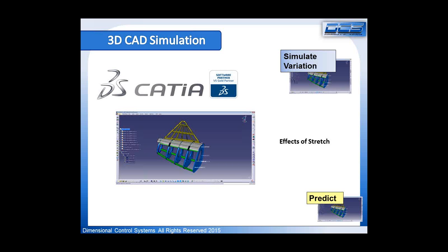And in this case, when we talk about things like the effects of stretch, this is a real-world example. If you go out, you would find a number of cases on aircraft skin assembly and the variation occurring in aircraft skin assembly due to the clamping and drilling and riveting process, and the effects that are induced into the skin as part of that process, and from a deformation perspective, and then what happens when this tool is unclamped, and what happens relative to all of this force or stress that's induced into the assembly, and how to start to consider that and compensate for it.